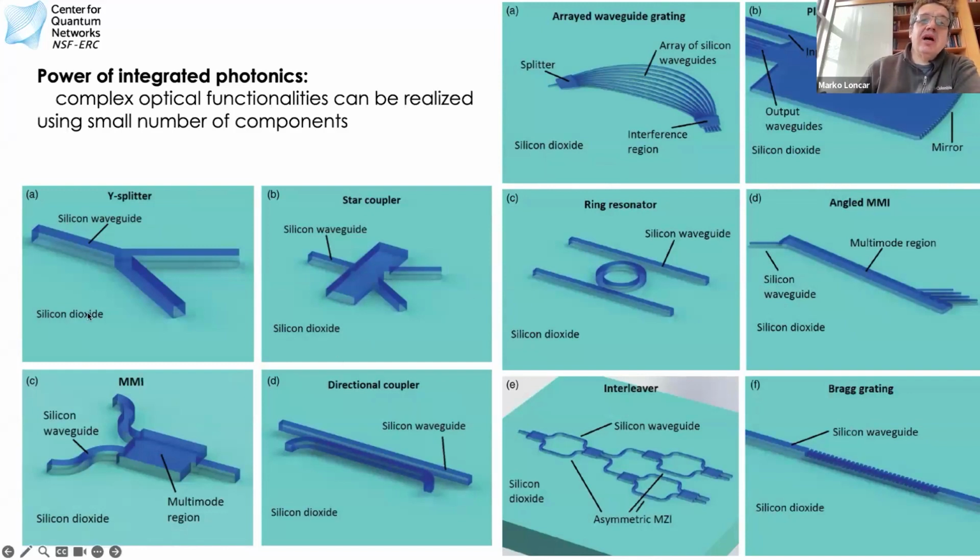Basically, we talk first about waveguides, and then we'll put two waveguides together to make various types of couplers. These four devices here are splitters, directional couplers, like here, multimode couplers, and interference-based couplers. We will not talk a whole lot about resonators. I'll show maybe some pictures, but a resonator is nothing but a bent waveguide in one of its forms. We will talk a lot about interferometers because they're really important for quantum photonics, in both passive and active versions.